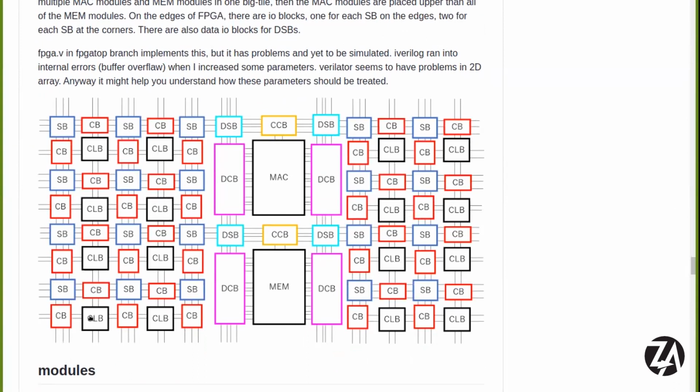And so in this sense, it's not very optimized for connectivity, because if you look at a modern Xilinx chip, for example, there are these big thick wire channels between these tiles that run different spans horizontally and vertically, and we kind of do away with that for simplicity. Every tile is basically just connected to its neighbor, and so to get from one tile to a couple over, you have to connect through the neighbor's switch boxes, and so that's slow, but for our purposes it's fine. But yeah, this is basically it.